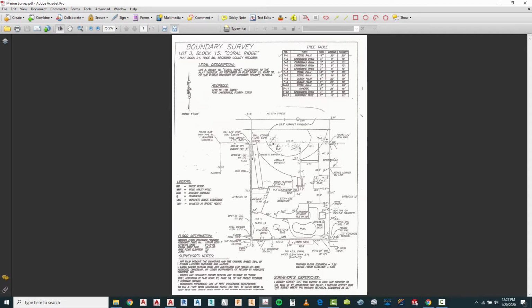I think one of the most important things is to not start the drawing and start designing until you have that information regarding the property. This is what we would call due diligence. So what we have is an address for the property here at 2718 Northeast 17th Street, Fort Lauderdale, Florida. What we want to do is find out what zoning that represents in the city of Fort Lauderdale and what some of those restrictive requirements are.